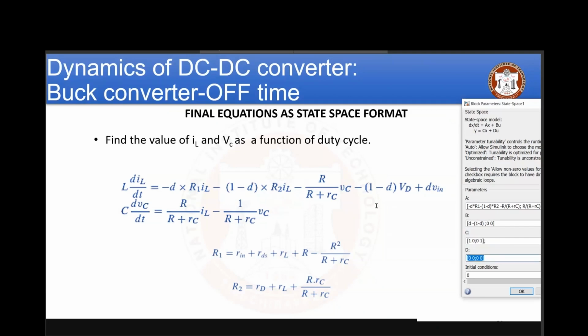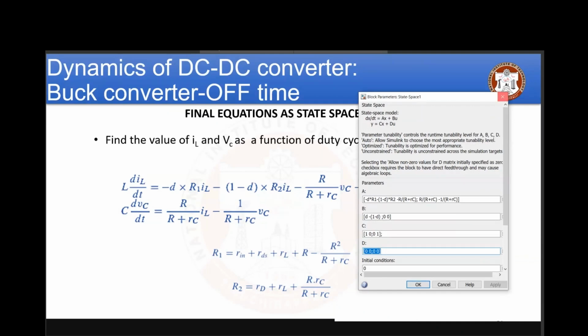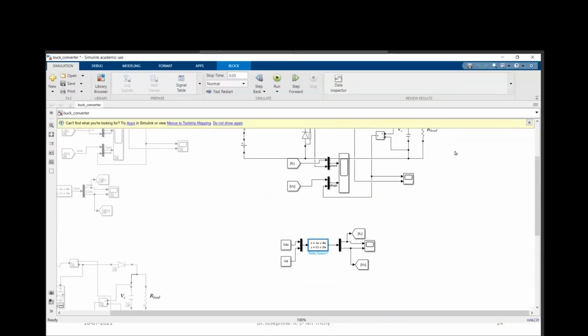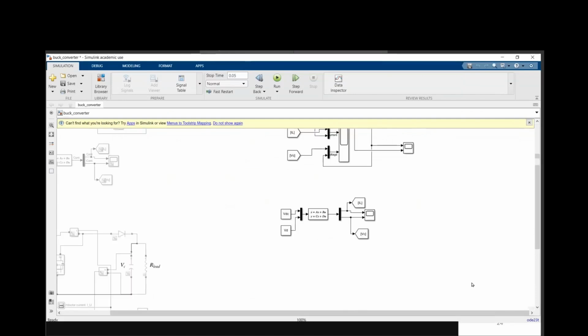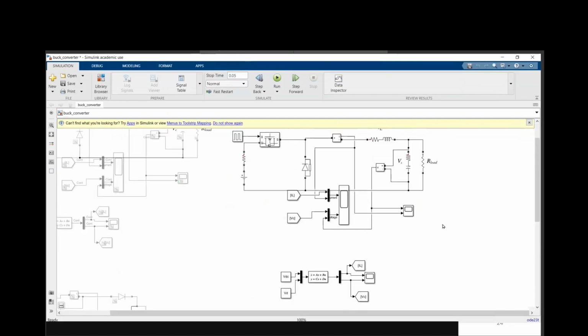See, the average model is not recommended to see the waveform structure. Only the simulators, the simulating blocks that MATLAB is giving, are good for finding those structures, because they use solvers like ODE, trapezoidal, or Euler's methods, backward Euler's, something like that, to solve this equation and get the output. But in case I use the average model, see, my simulation time is 0.05.